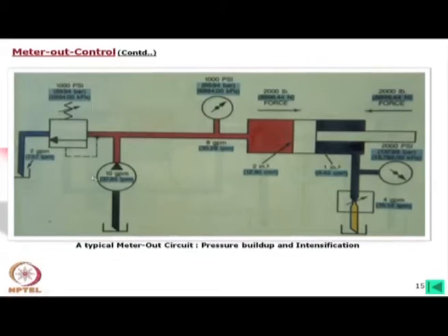Now, here I have shown this figure, and I will give you the note, from which you will have a better understanding. If you look here, it is 1000 psi, the pressure relief valve setting, and here it is a 10 gallon, 37.85 liters per minute flow, and the setting pressure is 1000 psi. As this is a flow control valve, it will normally go to the set pressure and there will be some flow from this side, because position is being controlled.